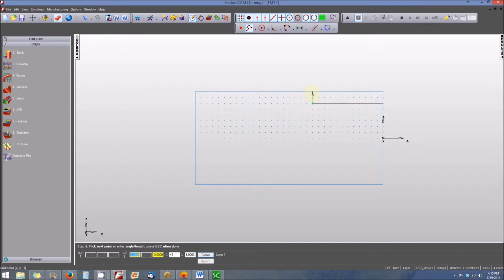And then we'll bring it up to create the shoulder. And looking at the drawing, there's a 1/4 inch radius in the corner. And that's complete. And now we will need to chain that curve, and create. This is now curve 1.